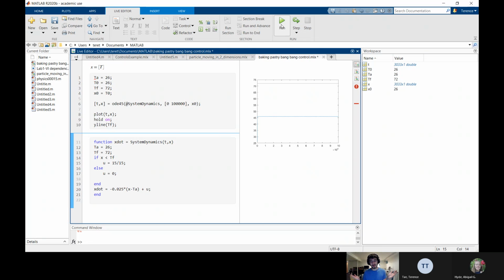You need a powerful enough control input to actually control your system. So this is a good example of the limits of control. There's a limit to how powerful our oven is. Oh, that's what I was saying with PID. It might say you need to apply like 5 million degrees per second, but that's not possible. So oftentimes if we're using PID, we'll just clip it at wherever our maximum is. But there are more sophisticated methods for control that are aware of the limitations.